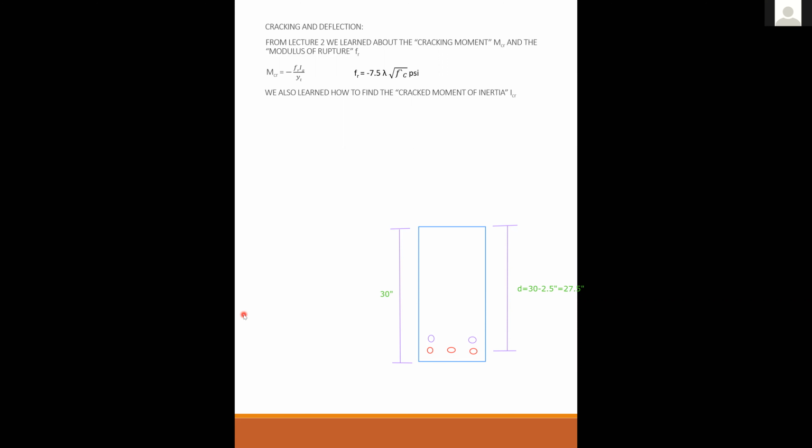Right. Okay. So, but hopefully you don't give us one like that. But in our case, can we just make it even so that I know that you're above the requirements? You're more than above the requirement, but it would be easier to find the centroid for that one. Well, it depends. If I said use a certain size bar and the answer is 5 of those bars, then you got to use 5 of those bars and calculate where D is a little bit more accurately.